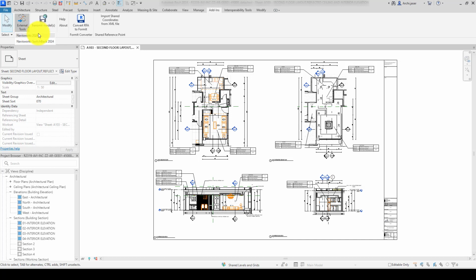So the package will not be in your system now. You need to go to your IT, guys, install the Navisworks Exporter, then you will have this tool. It's not only about downloading REVIT or installing REVIT. It's not only about installing Navisworks. Then definitely you will separately install also Navisworks Exporter from REVIT to Navisworks. Then you will have this option.